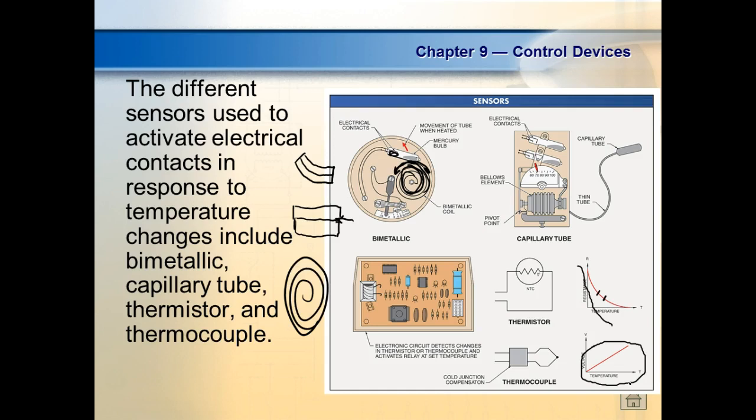What a thermistor does is it varies its resistance. So a thermocouple can be used by itself, a thermistor can't. A thermistor, we're going to have to power it up. Normally to power it up, we have to put in at least two resistors, because if I came over here and put one thermistor, the voltage would be constant.